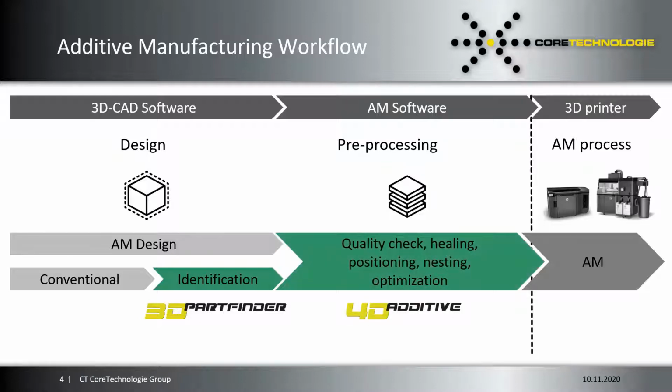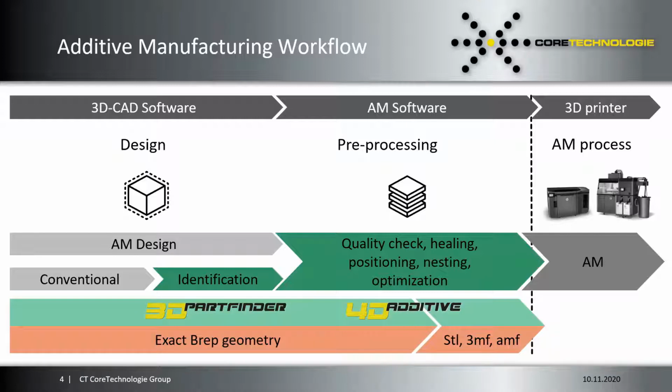And for additive, which is today the main focus, there are innovations and new functions integrated in this solution for checking the quality of all the models, healing, positioning, nesting, optimization, and so on. The most important thing to know is that in the entire process, the native CAD formats and the exact BREP geometry are used.